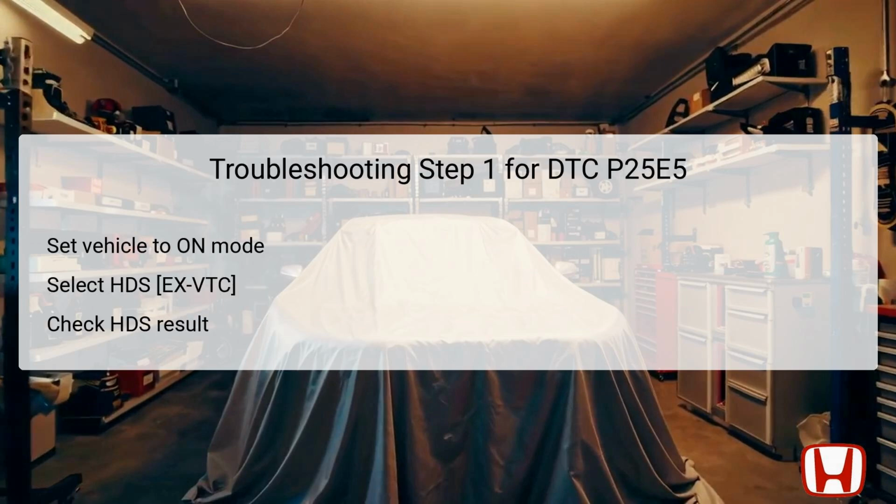For the troubleshooting of DTC P25E5, begin with Step 1 by ensuring the vehicle is in the on mode. This preliminary action prepares the system for diagnostics. Once the vehicle is in the on mode, access the Honda Diagnostic System, or HDS, and select the EX VTC. This function focuses specifically on the Variable Valve Timing Control system. Subsequently, observe the results displayed by the HDS. If the HDS reports "not okay," this indicates that the fault has been successfully duplicated and further diagnosis is warranted.